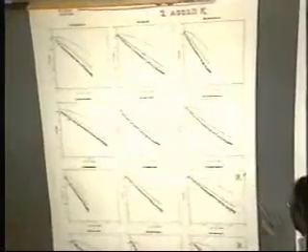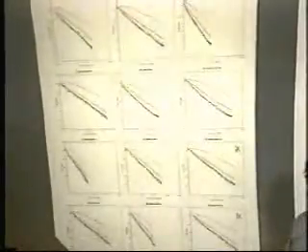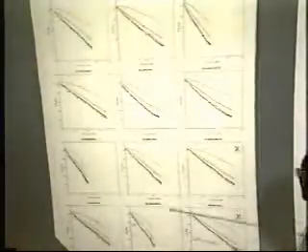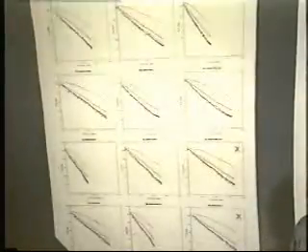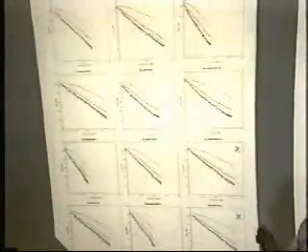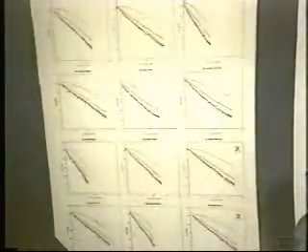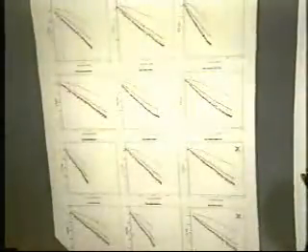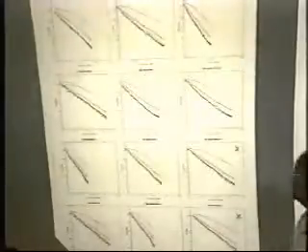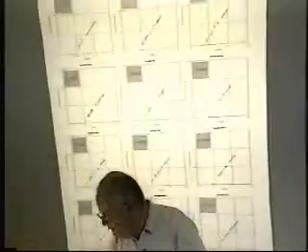I mentioned to you earlier that we had to add a couple wells down here, but look at the match of the physical 72-hour shut-in and the build-up of the model, as compared to the actual physical 72-hour shut-ins and drawdowns in the well in the field with backflow and everything else, and everything occurring simultaneously. And you can see it's an absolutely perfect match. All wells simultaneously on pressure versus Q. There's the match of deliverabilities on each of the wells simultaneously.